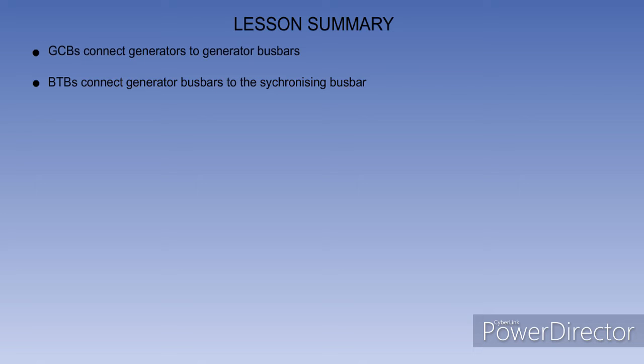To operate the generators in parallel, they are connected through their respective generator busbars to a synchronizing busbar by bus tie breakers or BTBs. The synchronizing busbar has no electrical loads connected to it.